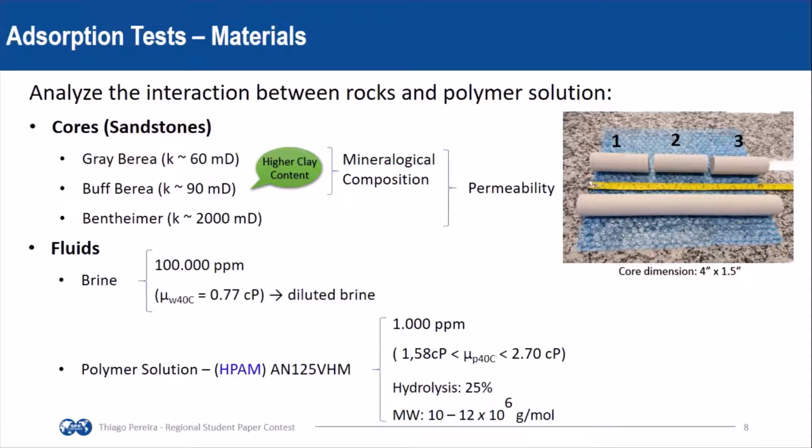About the fluids, we used a brine that mimics the formation water of a Brazilian oil field, and the polymer used was a hydrolyzed polyacrylamide AN125 VHM with a hydrolysis degree of 25% and a molecular weight of 10 to 12 million.